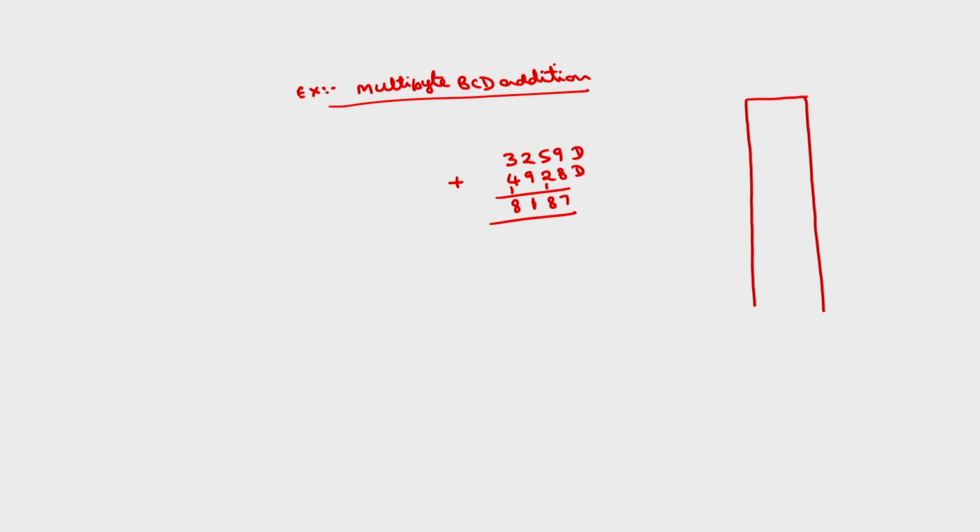Same data segment, say starting address is same 50,000 H, ending address will be, if it is 64 kilobytes, 5FFFFH.